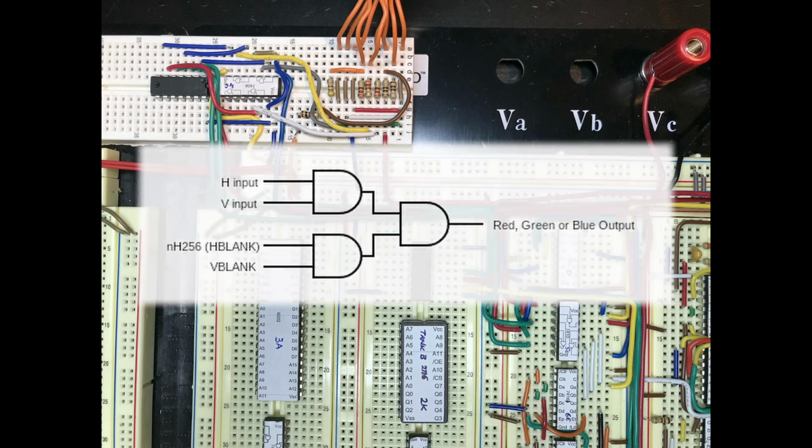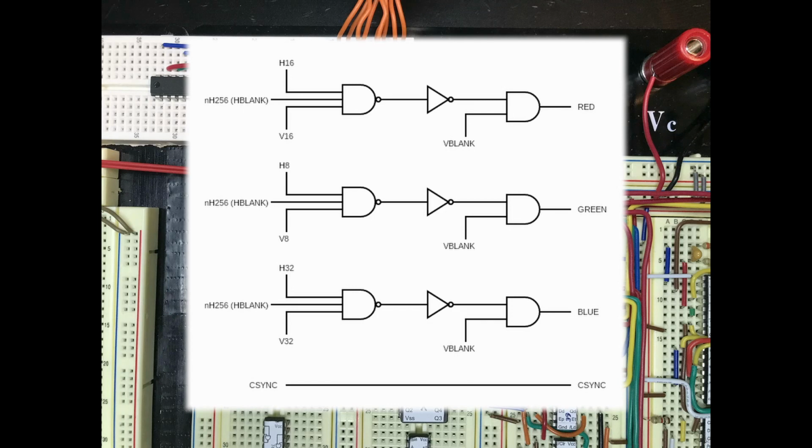Unfortunately, I only had the parts making up this board, so I had to get a bit creative using a 3-input NAND, reversing the polarity of that with a NOT gate, and then ANDing that output with the 4th trace. It's the same as a 4-input AND gate, but it's just a bit more work.